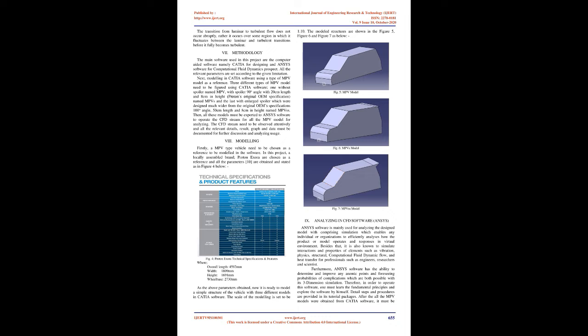L equals 1/2 ρ V² CL A, where CL equals coefficient of lift, ρ equals density of air, kg/m³, A equals frontal area, m², and V equals velocity of vehicle, m/s.